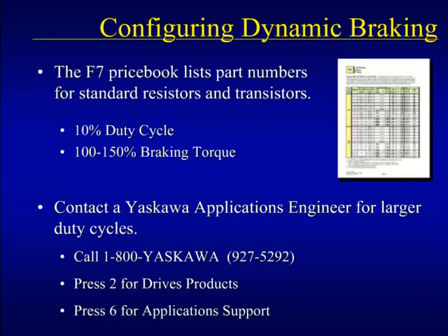On applications 5 horsepower and below that require only a 3% duty cycle, a heatsink mounted dynamic braking resistor may be used. However, for applications requiring larger duty cycles, contact a Yaskawa applications engineer about properly sizing the dynamic braking packages.